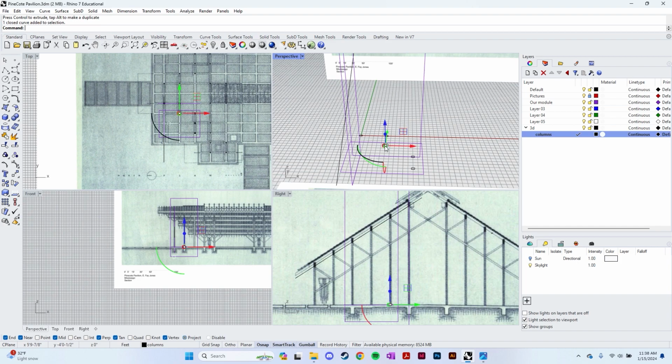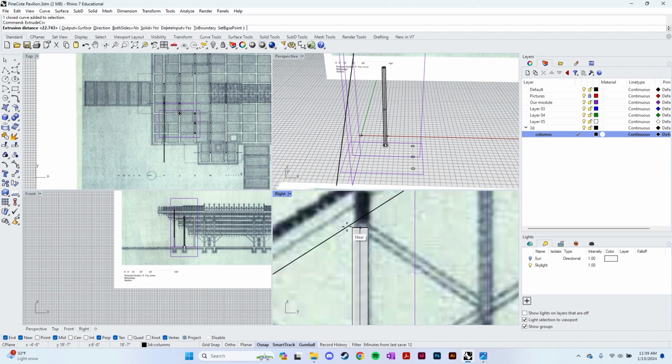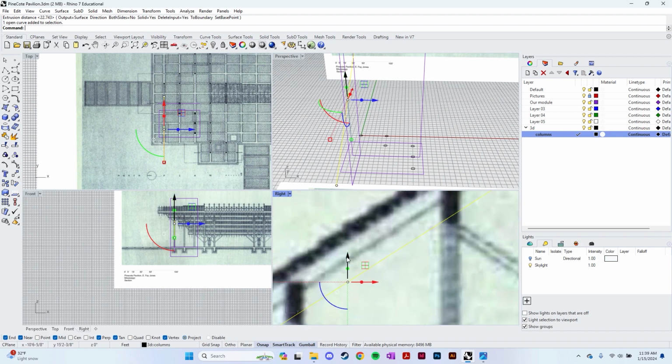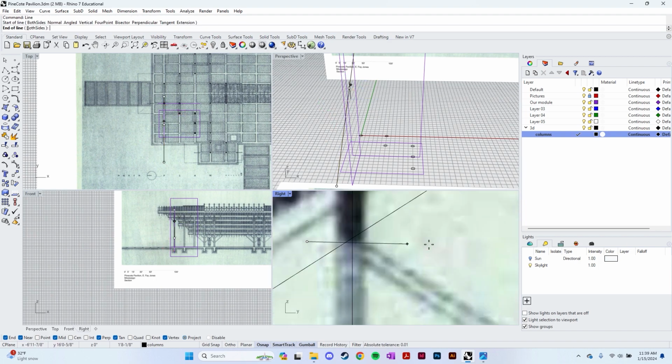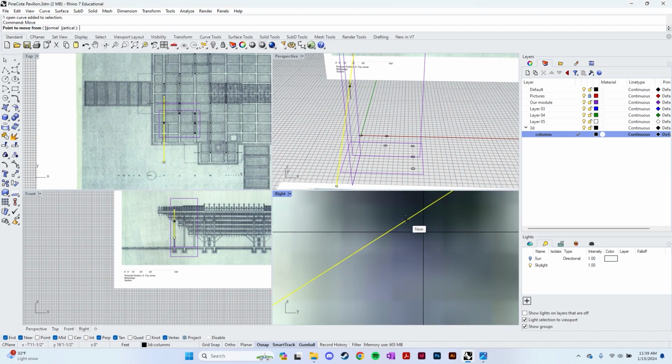When we go ahead and try to use the actual extrude command, we can see that the snapping of the column is actually centered. So we need to make sure that our guideline intersects with the center of the top of the column rather than one side or the other. If you want to be really verbose, you can set up guidelines and make sure that the intersect snap is turned on, and you will be able to snap your selection right to the intersection of those 2 lines.